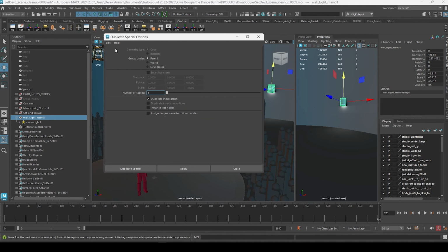I'm going to start troubleshooting this. So I'm going to go Window, General Editors, Attribute Spreadsheet, and go into the Arnold tab. And this is all the lights that I have selected. And I'm going to start with exposure and start cranking it down. Yeah, so it loses that hot highlight. So an exposure of 12 for now seems to be working.